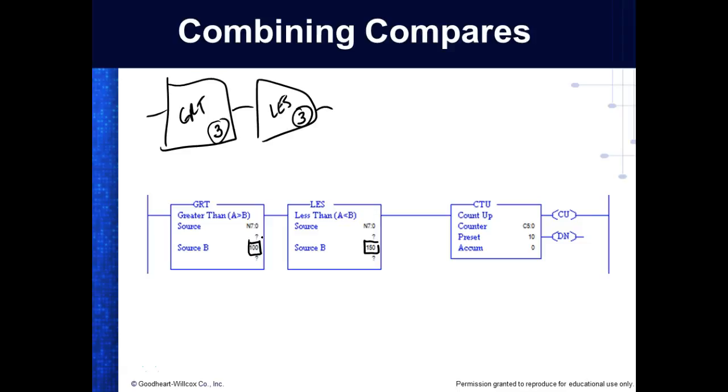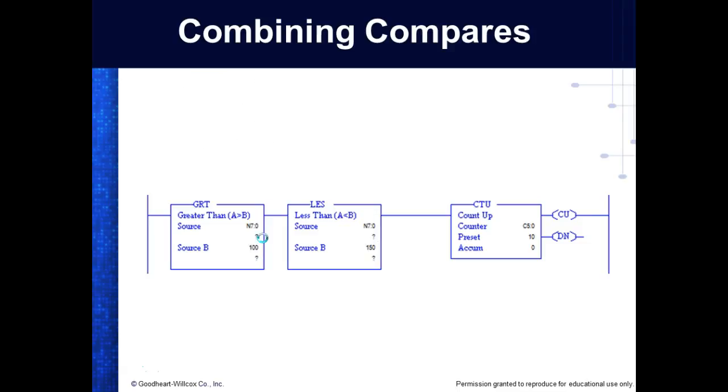And is NOR going to be your exclusive function? No, these are not exclusive functions. How would you get NOR? You wouldn't use them on compare instructions. You would have to go through contacts or something. So, ANDs and ORs are basically compare instructions. We're trying to see if something is true or not true. Are we okay? But I guess if you thought about it, you could probably implement an exclusive OR for these guys without using contacts.